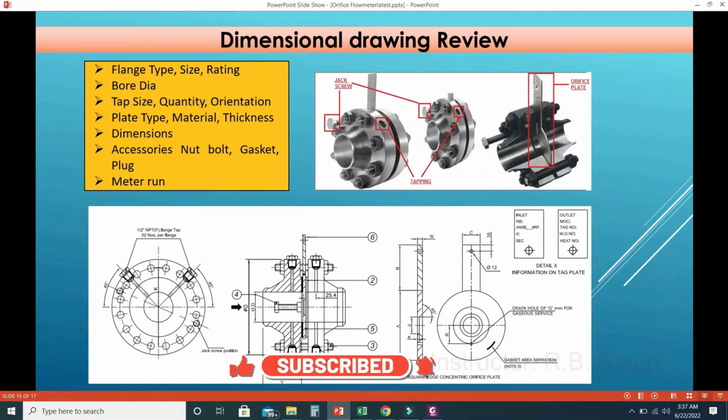Also dimensions: face to face dimension, the vertical dimension. All these details we have to check whether they have provided or not. Again they have to provide the BOM, like nut, bolt, gasket, plug, meter and whatever items we are purchasing as per our PR data sheet, that we need to capture in the dimensional drawing also. This will be quite a big document, and somewhere they have to provide the bill of material also with quantity and material.